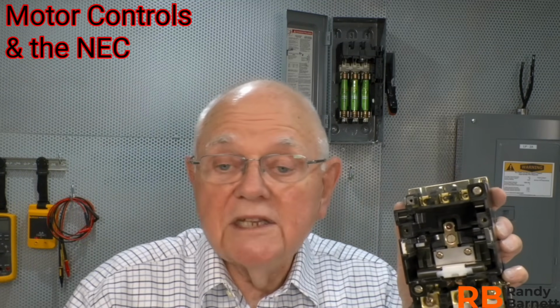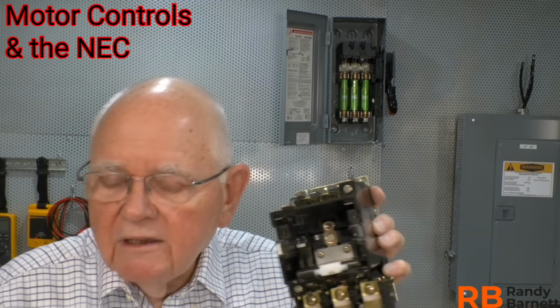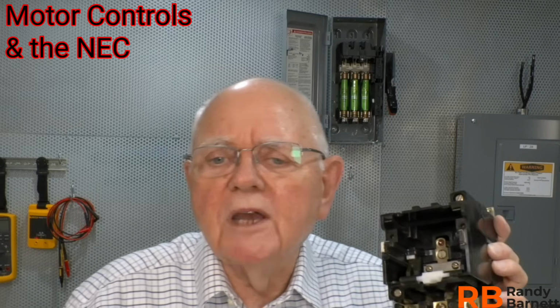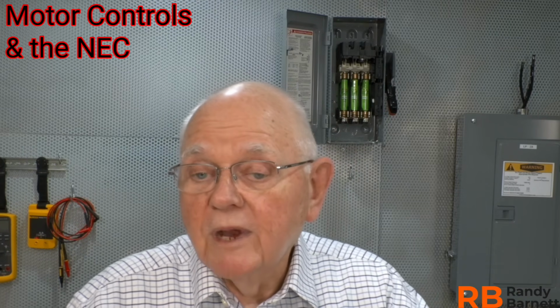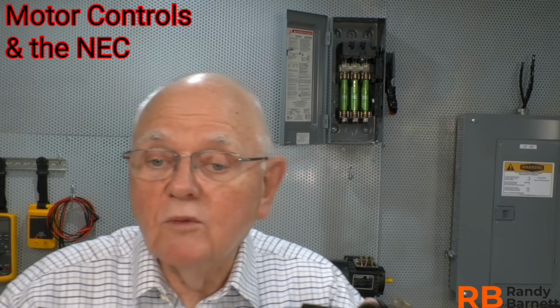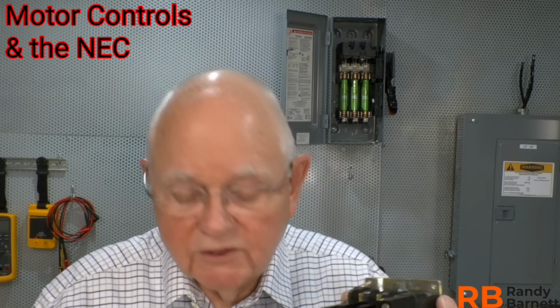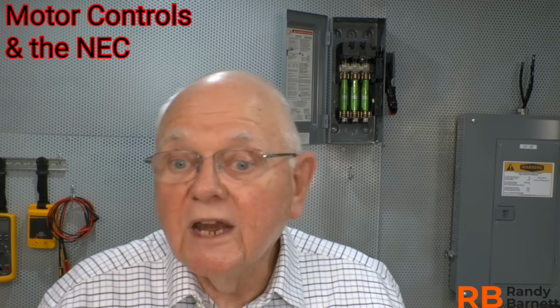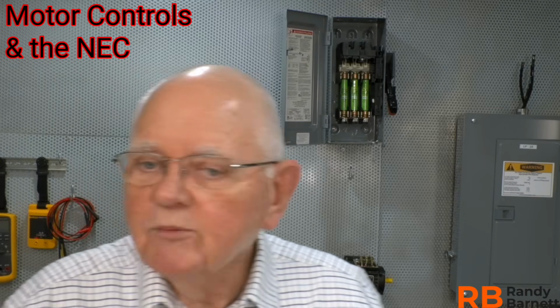So I can clean these contacts on a NEMA starter. I can replace them if need be, and so on, inspect them. Certainly I'll do measurements on them, all part of my periodic maintenance program. My measurements, I'm probably checking voltage across the contacts, or more likely, what am I doing? I'm doing a low resistance ohmmeter check across those contacts to make sure that they're within specification, that they're not getting dirty. Now, if it's an IEC contactor, I can't pull that one apart.